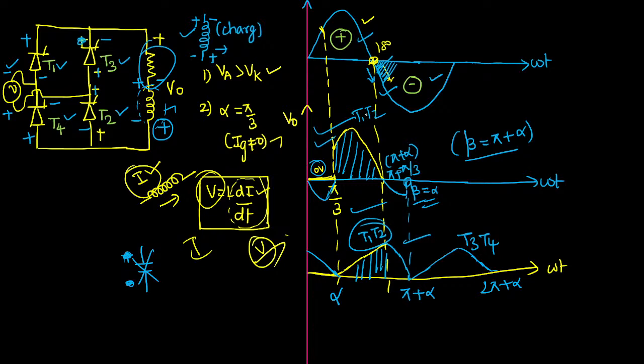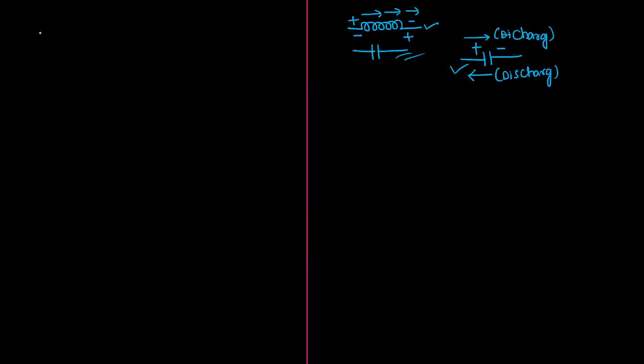Okay sir, fine. So it's time to calculate the average value of the thyristor current. Here I am saying that I naught average will be equal to the average value of the thyristor current, because I have drawn the waveform of the output only, not the thyristor. But in case of a fully controlled bridge, whatever current goes through the thyristor, the same current goes through the output also. So both are the same, there is no difference. Then how will you calculate the average? Average value means the fundamental formula is area divided by time period. You all know this fundamental formula.